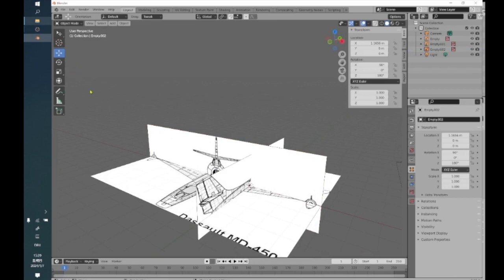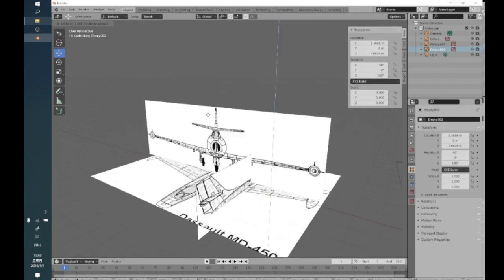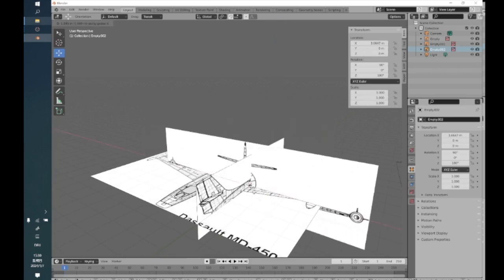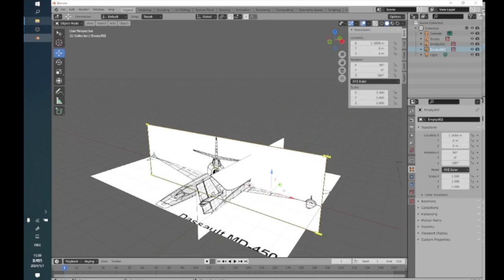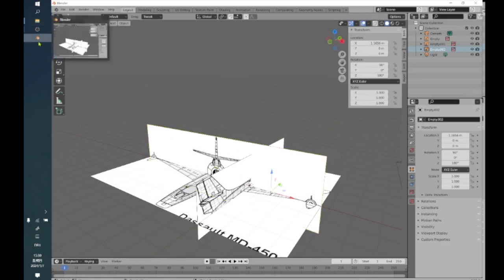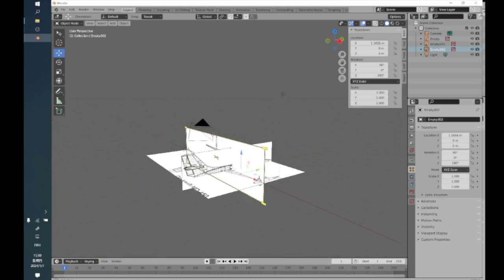So that's why there is the other way of moving the images, which is click on the image, hold and move around, and then constrain along the axis if needed by using the keys X, Y and Z. And as I said, to scale, around the cube, the corners. Here it is a little box at the corner. If I do the same in Blender 4, there will be a big box on the side, but it's still the same.